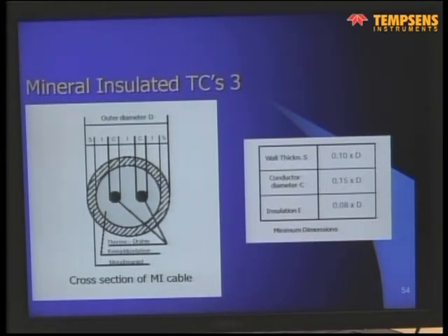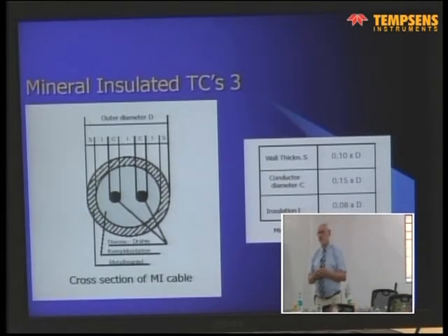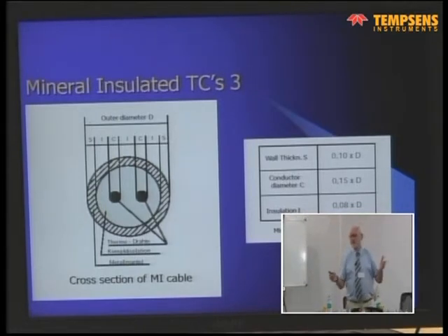And the blocks for the insulation material are normally 4 inches long, approximately 100 millimeters, with 2 or 4 holes, and you feed the wire into the holes and then the entire system into the pipe. Pipes are normally 6 meters, or 6.5 meters. Yes, and then the production process starts.